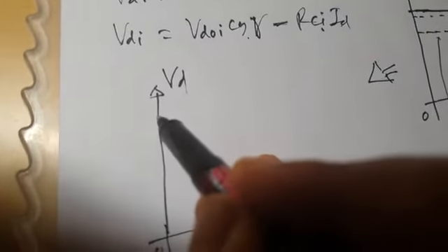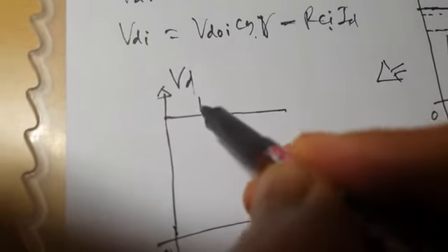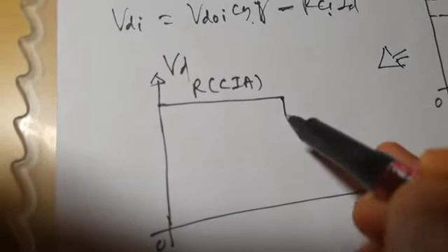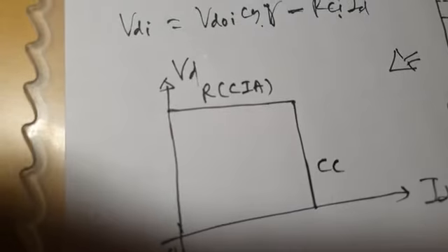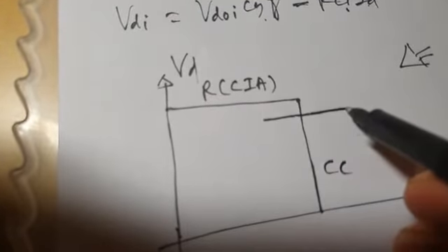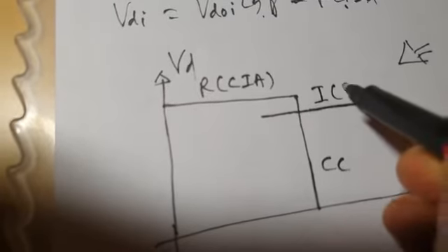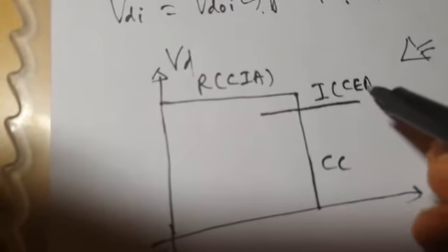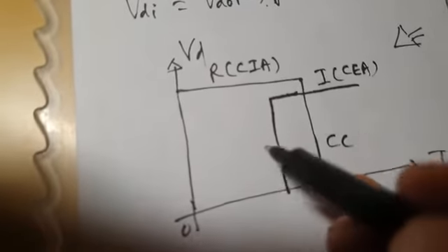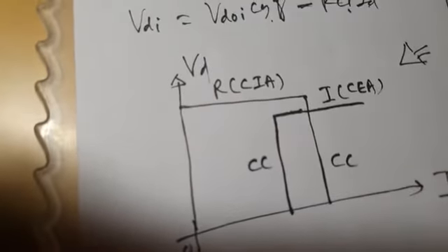This is the rectifier characteristic, which comprises constant ignition angle control and constant current control, CC. And then this is the inverter characteristic. It has less slope. It comprises constant extinction angle control, and constant current characteristic is also given to the inverter.